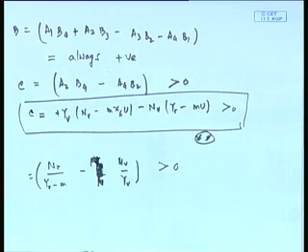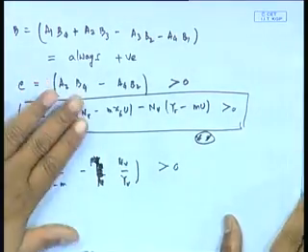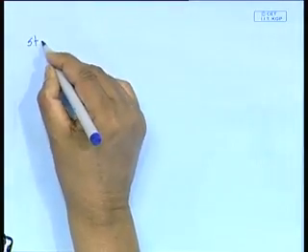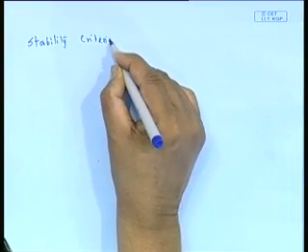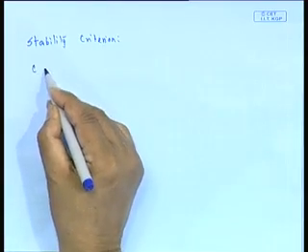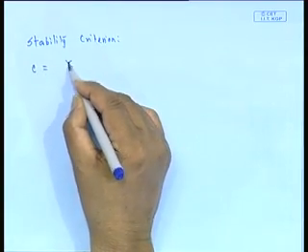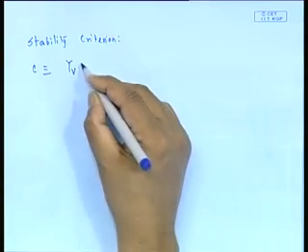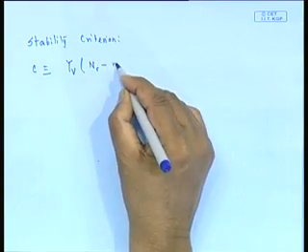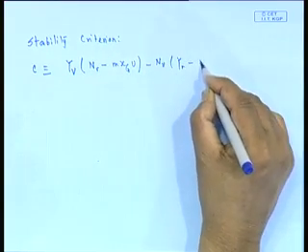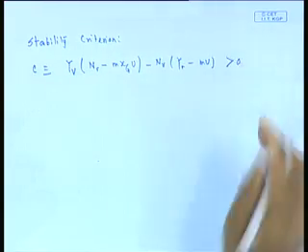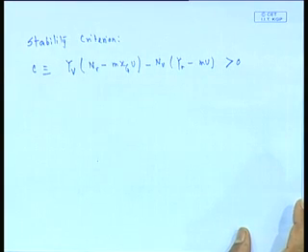The interesting point that we have now ended up getting is that I must have my hull with the values YV, NV, YR, NR in such a way. Actually this is so important that I am going to write it again in a big way. This is what the condition is.